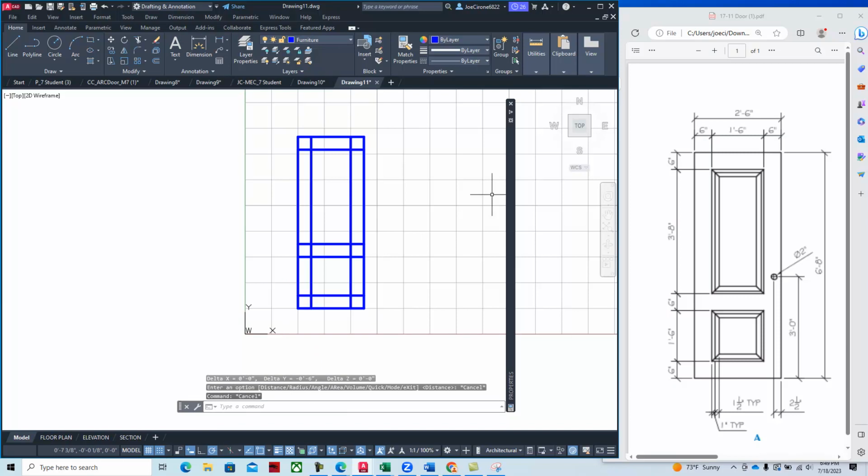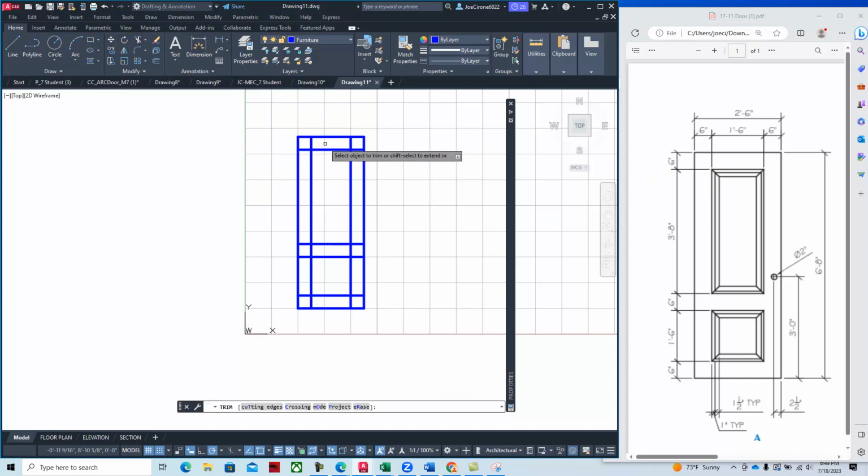So as we start to analyze these drawings and work with it, we're going to use the trim command to trim out this geometry, and trim is great. They've upgraded it. It's a lot like SolidWorks, where you can just kind of glide through these different areas you want to remove. And so I'm clicking and holding the left mouse button. You can also just click on it. That works as well. I think gliding is easier. You don't have to be as accurate.